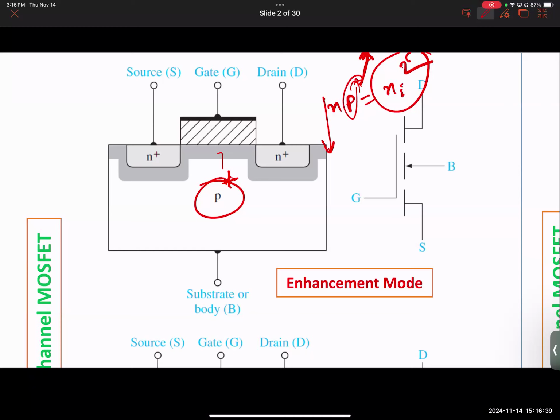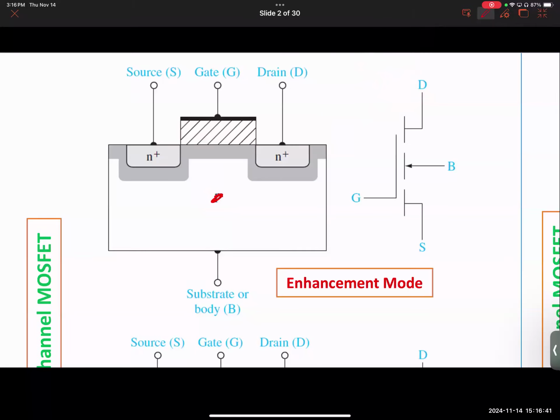Okay. Another quick question could be, why don't we just make it N type and keep it easy for electrons all the time? Then how do you turn it off? It's not a switch, it's always on, right? What is the use of something that is always on? You could have just used a metal instead, just connect them. So that's why there are reasons behind all of this.